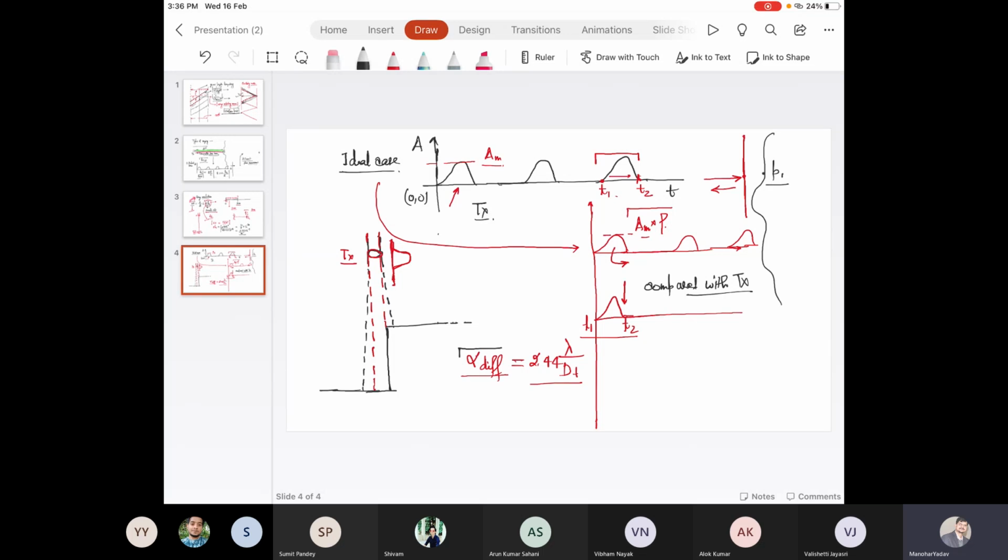So this is the reason why we have diffraction. Due to the diffraction, there is a deviation and dispersion, and that leads to a larger size of laser footprint compared to dt. So we can say that the footprint diameter is always greater than dt, due to the diffraction angle alpha. Our main objective over here: if this is the building, both surfaces are flat. This is the roof part and this is the adjacent ground part. Now see what happens. Again, it is represented by T2 and this is represented by T1.